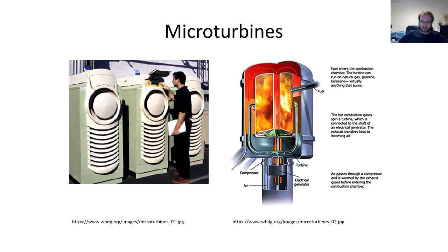Then the flue gas goes out through something called the recuperator and outside of the microturbine itself, where of course the turbine with the compressor on the single shaft has some net power output, which is converted to electricity in the generator. Then the flue gas exiting the system still has considerable temperature, and the heat of the flue gas is typically used for heating.